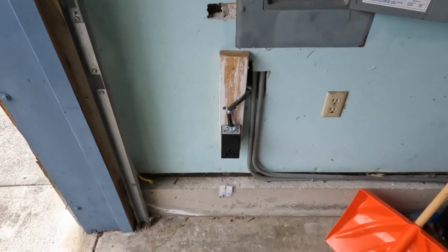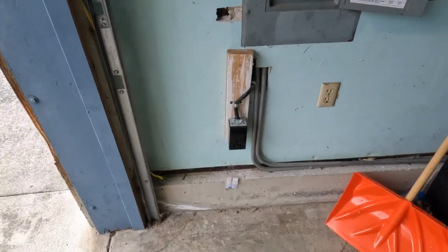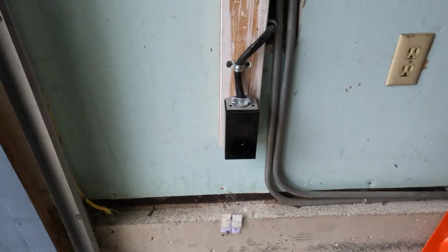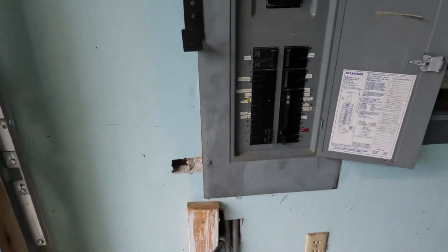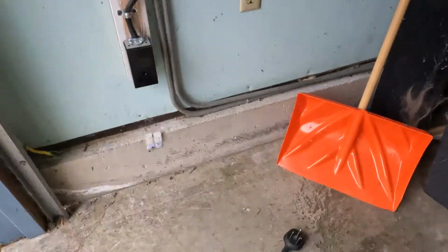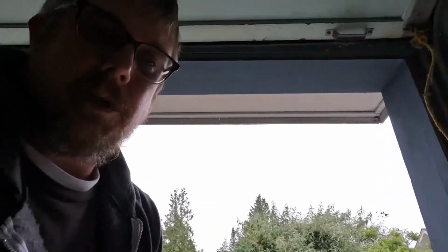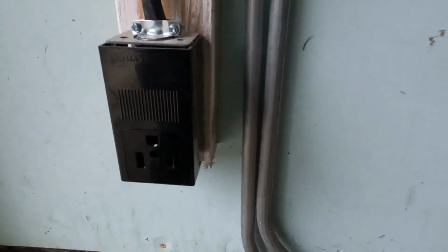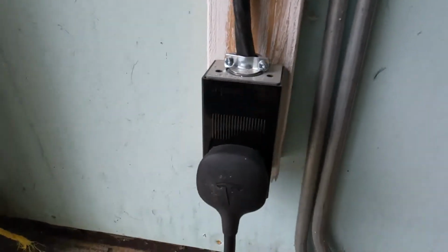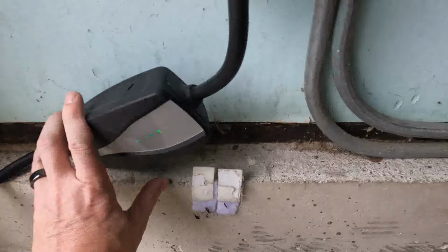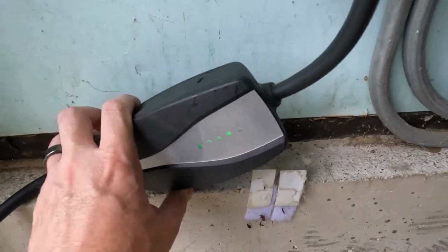All right, welcome back. So we're talking level 2 charging and the actual equipment in an example. And you can see here, I've got my NEMA 14-50 outlet, and it's connected to my panel. And then down below here, again, we've got our Tesla electrical vehicle supply equipment with a NEMA 14-50 end. I just pulled out the 110 adapter I had, and I put on this one. So we just plug this bad boy in to our outlet. We can see that our Tesla has lit back up and we don't have any indicated problems with our charger, or excuse me, our fancy extension cord.